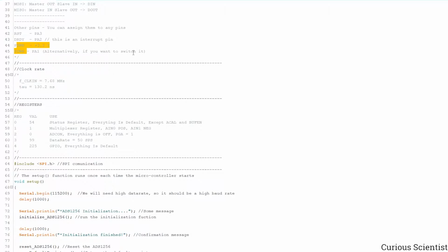So you should check your AD converter, and you should also check my video in the corner, because I made a comparison between several different ADS1256 boards, and I showed you that sometimes you have different pins apart from the standard SPI pins and the data ready pin. So you have to check that yourself. So I really recommend you to check that video.